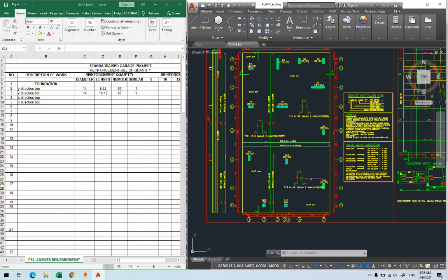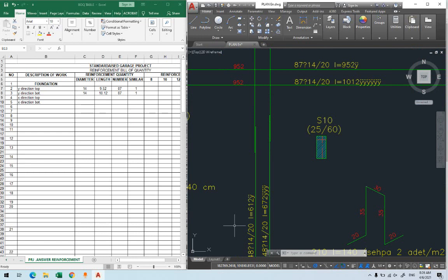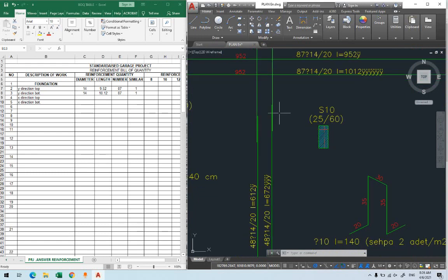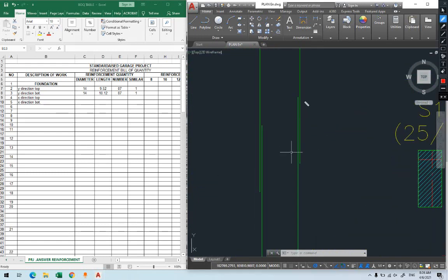And when we're providing it in two steps, there will be a distance where the reinforcement is supposed to come over each other. We call it splice distance. Now this distance can be 1 meter, it can be 50 centimeters, 70 centimeters. According to the code, there's a calculation for it. But practically, they put 1 meter. Some put the minimum 50 centimeters. Some put 1 meter here.